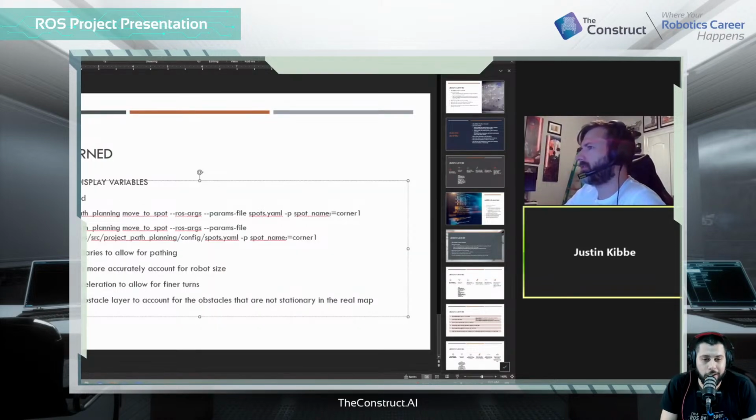Those are the hurdles that I had to overcome: learning how to decipher some of the error codes, and then adjusting the inflation boundaries so that I could actually move around, to give the robot some space to run. Adjusting the robot radius also helped.